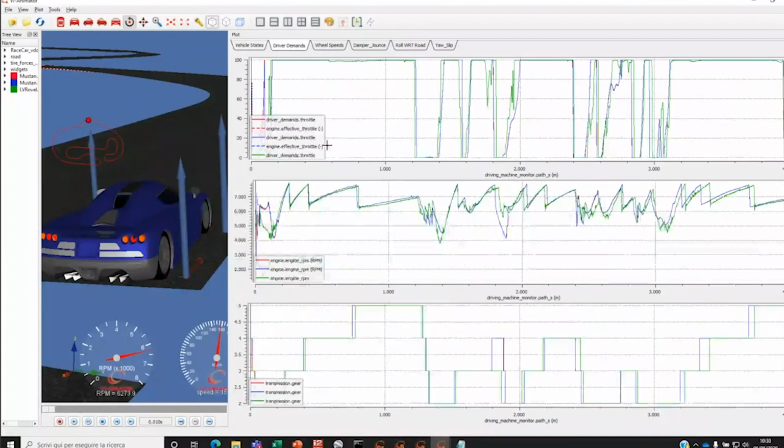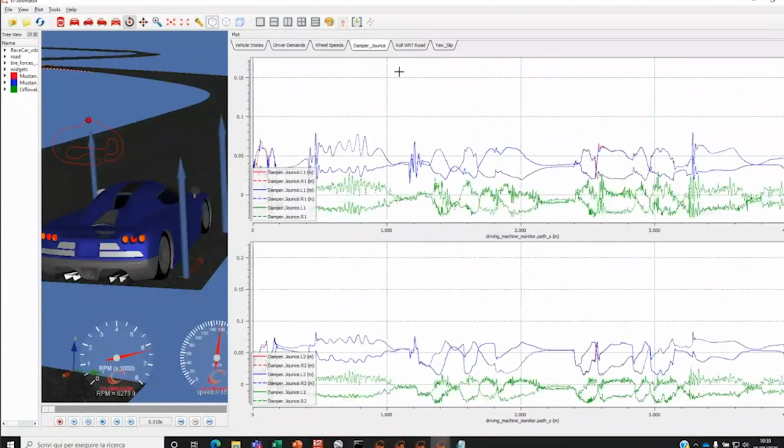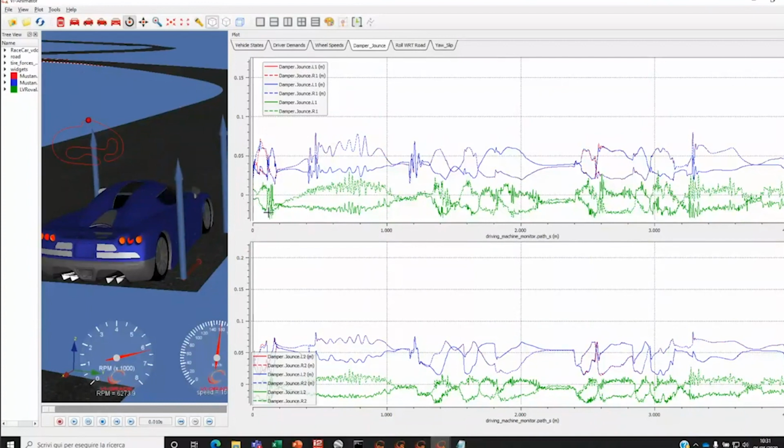So it is interesting that it's possible to come up very nicely to the behavior of the vehicle, let's say upfront to the track session. Also here you can see that the damper displacement are pretty similar. Of course, here we have some offset related to the fact that the measurement in the telemetry are offset with respect to the static condition, while in the simulation model we have the design condition as a reference. But the shape of the curves, as you see, is pretty close.